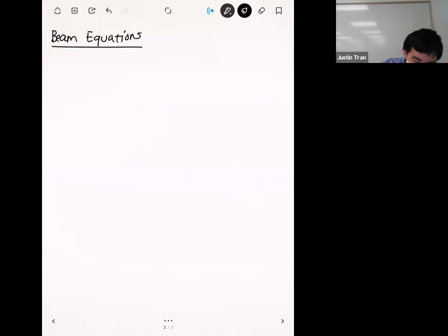Throughout this whole unit on the direct stiffness method, we've been solving these finite element problems essentially by hand, right? I've been giving you a system comprised of several structural elements. You've been forming the element stiffness matrices, assembling them into the global system, applying boundary conditions, and solving. There's really not much more we can say about that process. We've kind of done everything. The only thing left to do is to cover one last topic in terms of distributed loading.